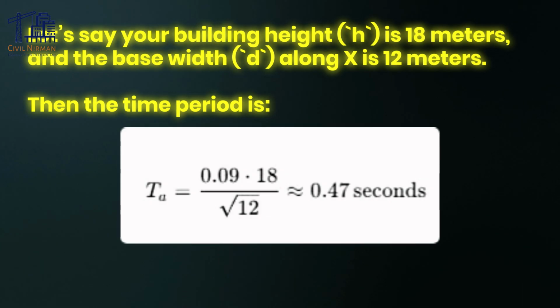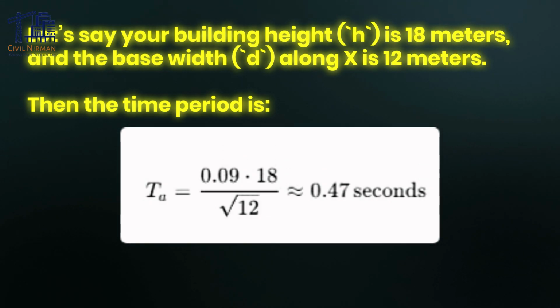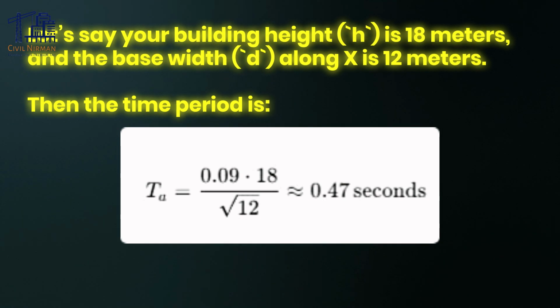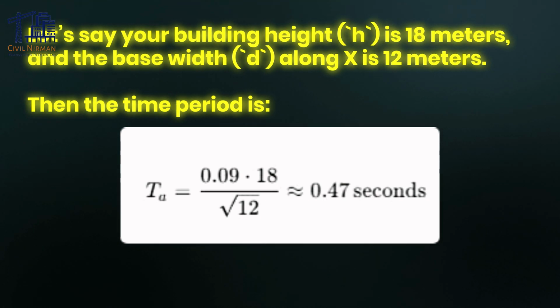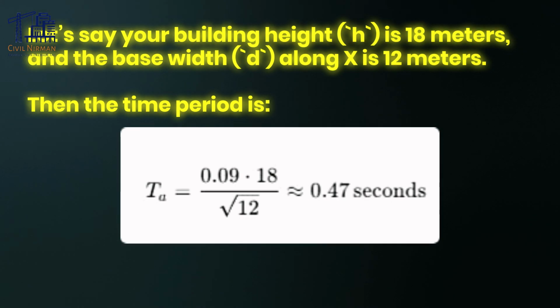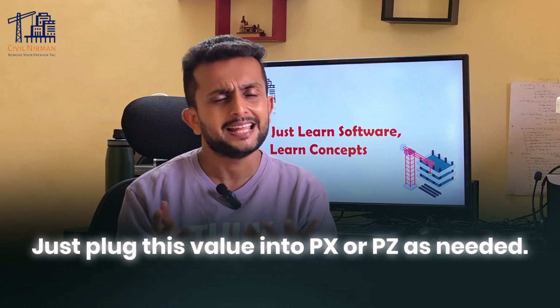Just for your understanding, let me take you through one example. Let's say our building height is 18 meters and the base width is 12 meters in the X direction. Then the time period that you will calculate utilizing this formula will be around 0.47 seconds. So just plug in this value into PX and PZ as needed.